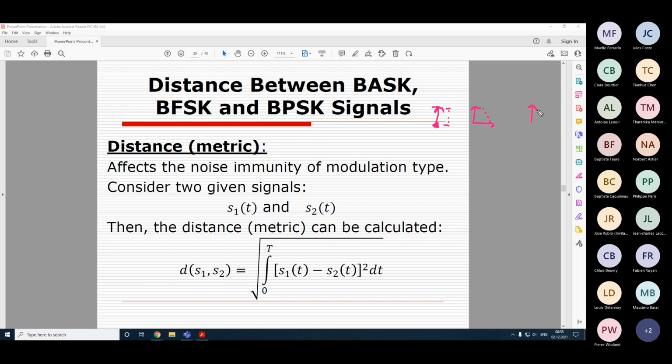And for phase shift keying, these are opposite phase signals, and the distance is even greater. So in fact, this is the maximum possible distance. If you rotate these vectors any other way, for example, like this, the distance will actually decrease. Yes, so this is the maximum possible distance we can get. And this is somewhat best for us if we use orthogonal signals.